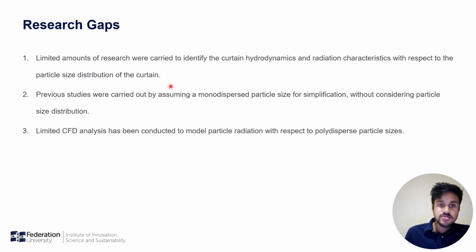These are the research gaps that I'm going to discuss within this research. There are a limited number of studies carried out to analyze the particle hydrodynamics and radiation characteristics with respect to the particle size distribution within the curtain. Most studies were conducted considering monodisperse size particles only. There are limited CFD analyses conducted to model radiation of the particle curtains related to polydisperse size particles.